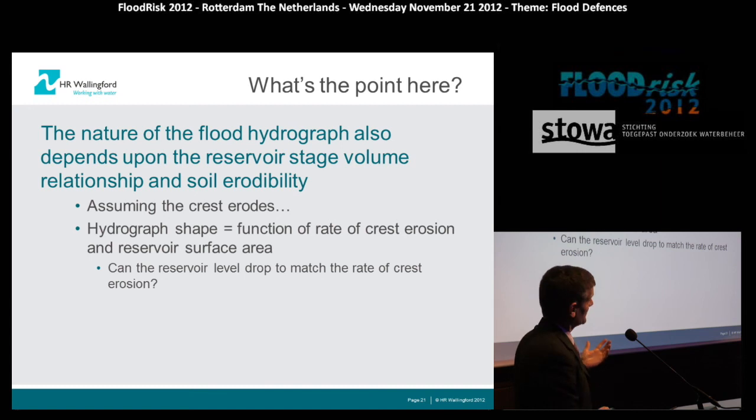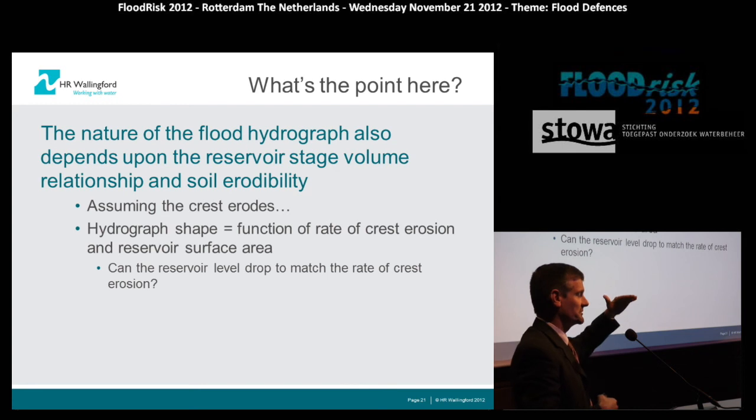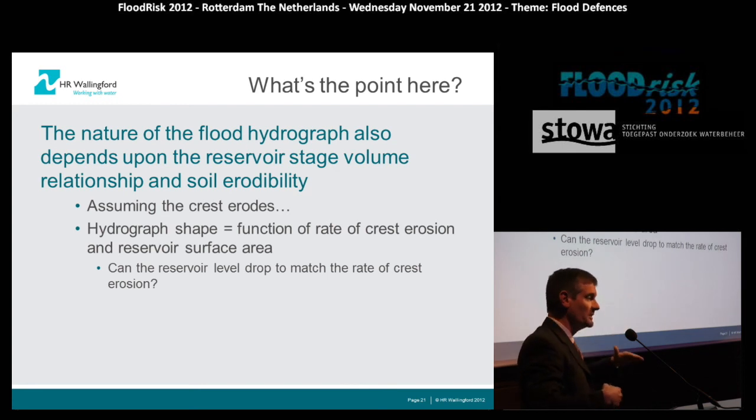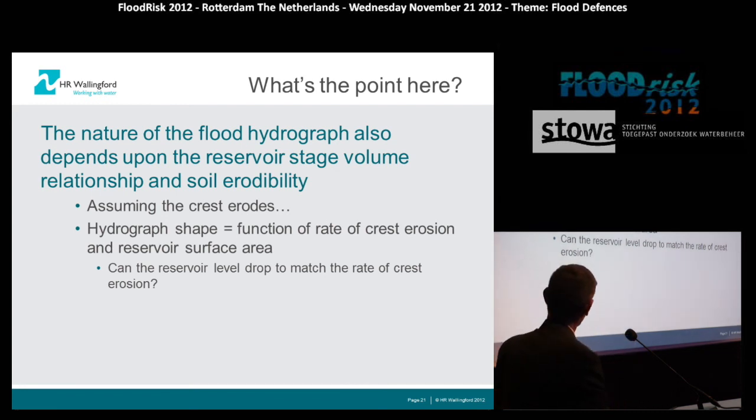The nature of the flood hydrograph also depends on the relationship between the soil erodibility and the upstream stage-volume relationship. If you consider how the crest erodes, you have competing processes going on here: the rate at which the crest is eroding down versus the rate at which the breach can draw down the upstream reservoir level. And obviously the rate at which the crest erodes down is a function of the soil erodibility.